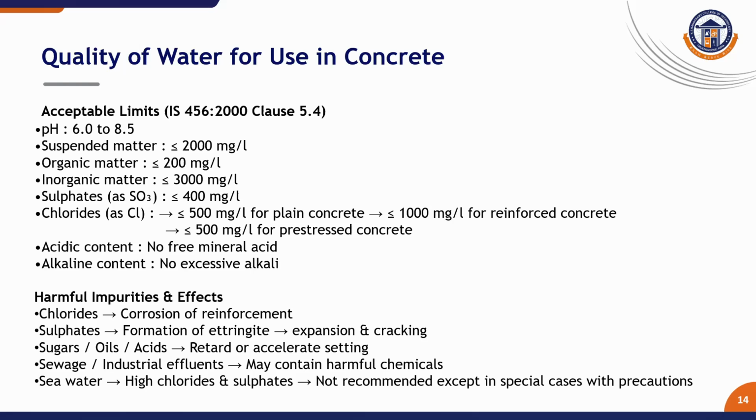Chlorides affect the corrosion of reinforcement. Sulfates cause expansion and cracking. Sugar, oil, and acid retard or accelerate setting. Sewage and industrial effluent may contain harmful chemicals. Sea water contains high chloride and sulfate, and is not recommended except in special cases with precautions.